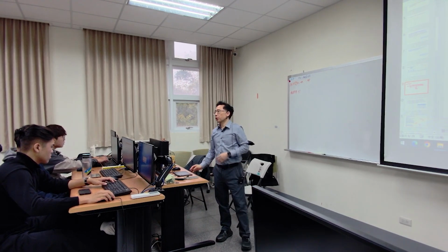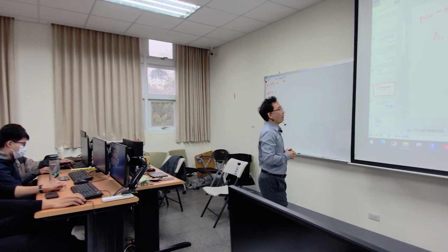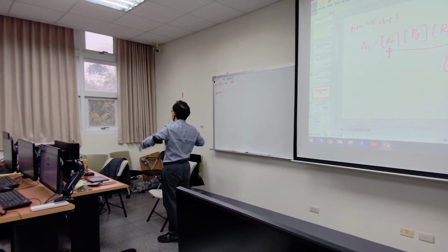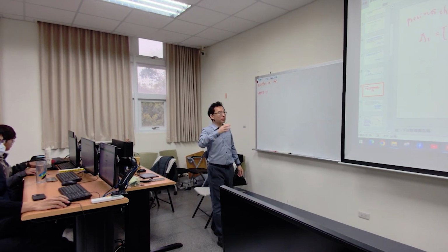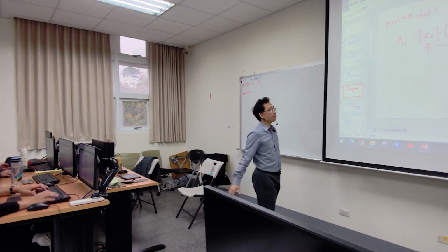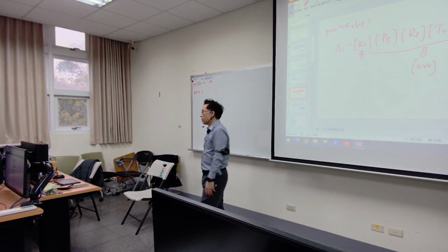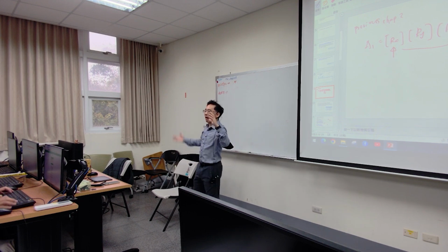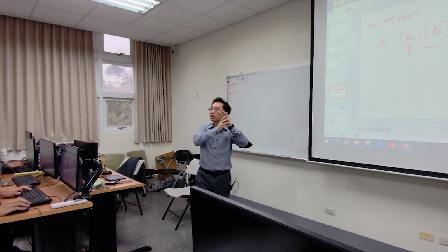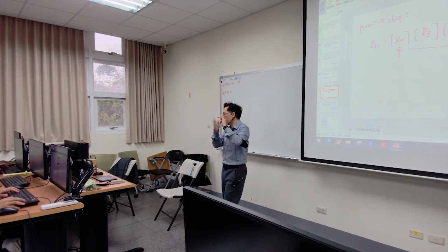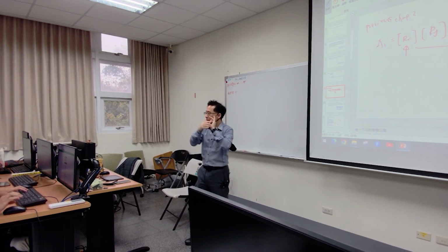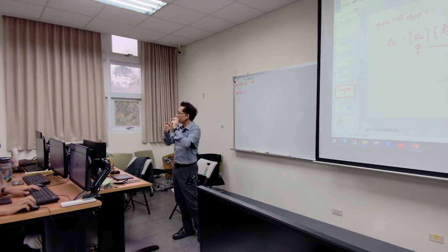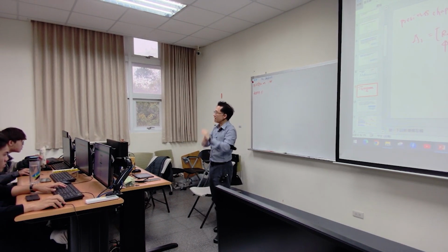I believe in chapter 2, we start here. We have all 4x4 matrices. Each matrix can represent rotation X, Y, Z and translation X, Y, Z together. So if I want to describe a joint, I can list all the parameters I have: what kind of degree of freedom you rotate with, X or Y or Z. If you did not rotate, still multiply the original one. And what kind of translation you performed in X direction, Y direction, Z direction.